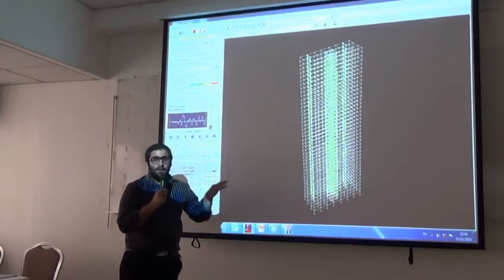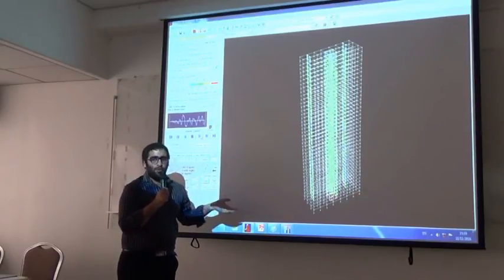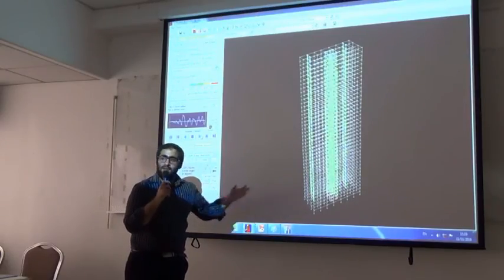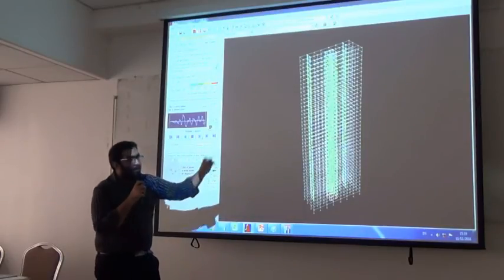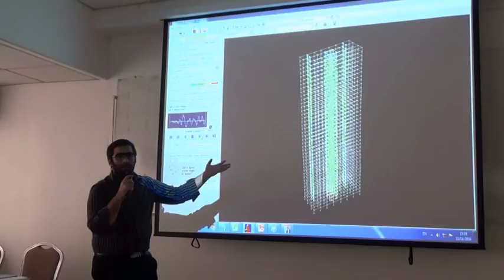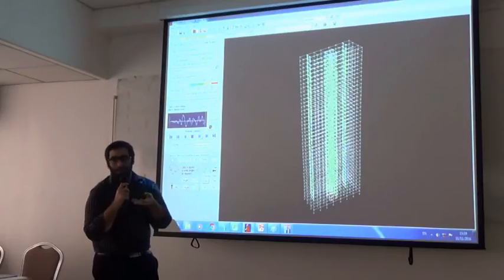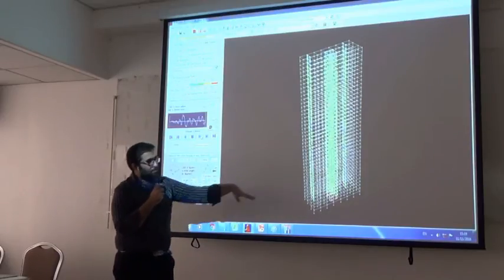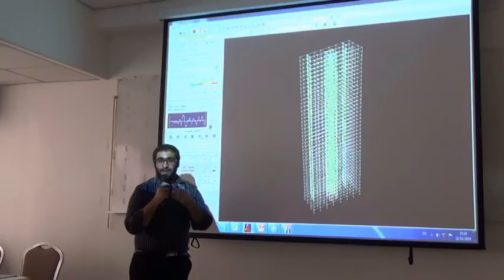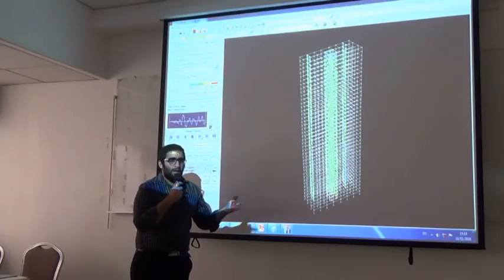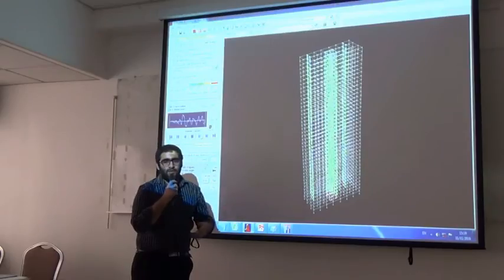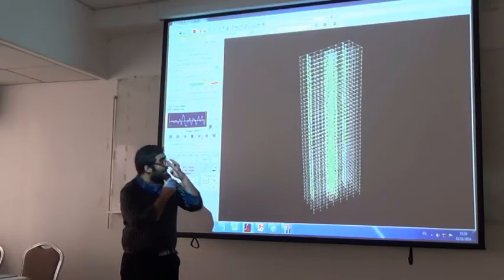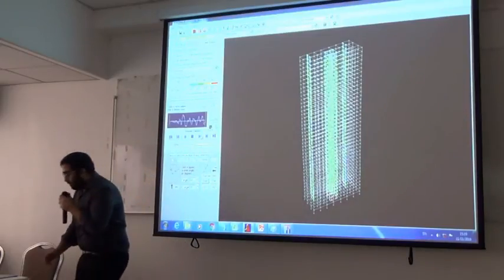So this is about the strain gauge that we spoke about when I was showing you the modeling part. We already spoke about it, and now we can see that we can get some results for those strain gauges that we had already assigned, right? The plot that you see over here is just the color, if you want to see, or if you want to put in your report or something like that. But generally, we will not use this plot to check our results. We have to know the number also. The color is not important. Color is just to show over here. So when we need to extract, we will extract the DC ratios for the strain gauges also. There are ways to extract it. I think just the same option that you see on the top.